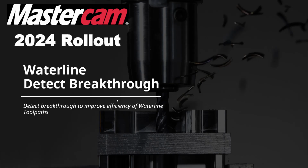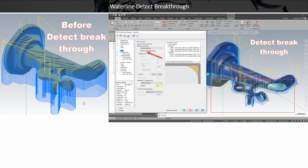I also have an enhancement to my waterline in 2024. In 2023, we saw a detect undercuts enhancement in the OptiRough. So if you're rest roughing off of a stock model, and if there are undercuts to it, it wouldn't see it. It's like if you just poured water right over it, saw it straight down. So it would just keep cutting even though there wasn't material left. Didn't understand undercuts. And that was enhanced for OptiRough in 2023. In 2024, that same enhancement is added to waterline.